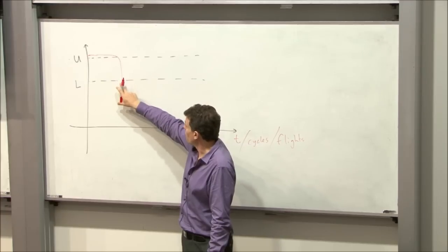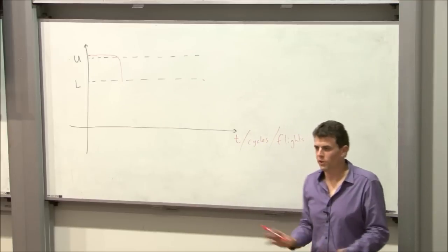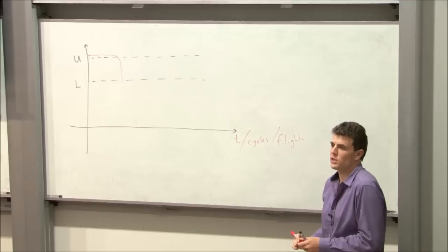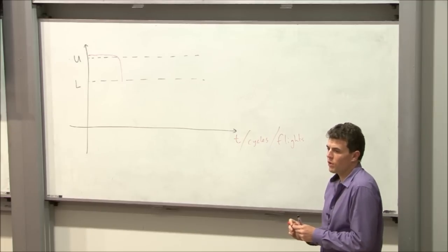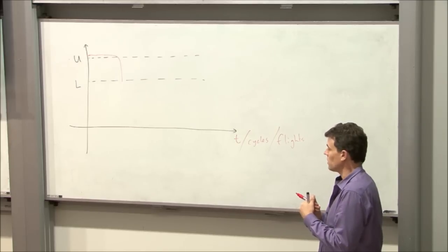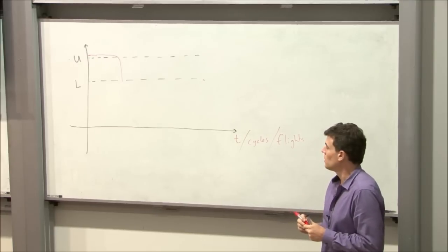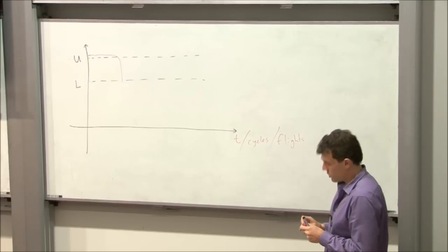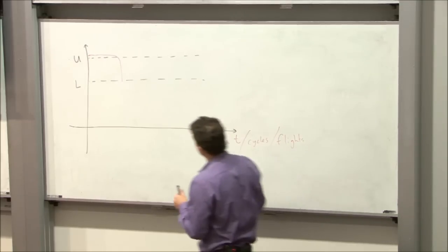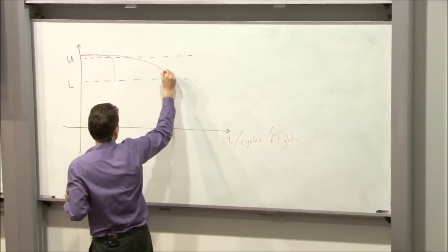So an example of that might be something that cracks very simply. So high tensile steels, for instance, have very low fracture toughnesses, so they tend to go from having undetectable damage to breaking fairly quickly. Some components, however, if we would travel along, would do something like this.